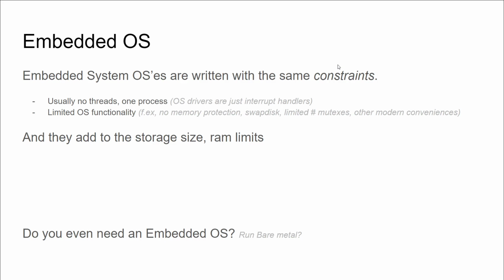But it's an option. Bare metal, as you call it when you don't run with an OS, gives you that extra bit of storage space, which is great if you're really storage constrained, and a lot of MCUs do run bare metal just because it's simpler.